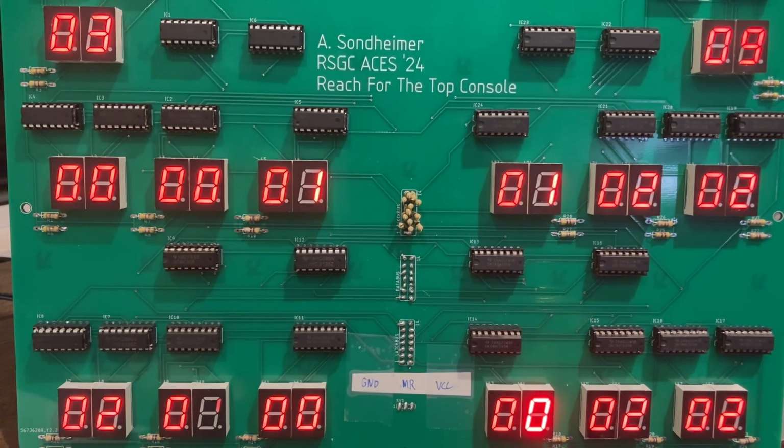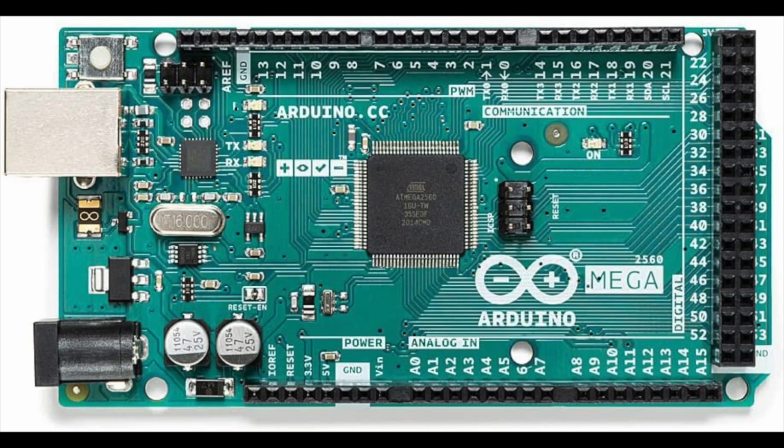In this stage of the multi-stage ISP, a scoreboard was built using a printed circuit board, 7-segment displays, and shift registers. It's using random variables to simulate a game. The microcontroller running this simulation is the ATmega 2560 or Arduino Mega development board. This board features much more storage space for code and variable information, as well as several more input-output pins than the Arduino Uno or Nano.